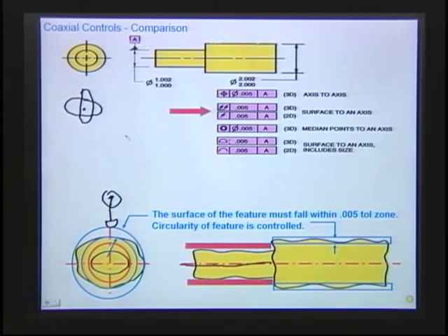So how would you check runout? Well, I'd probably do it the same way. I'd just grab a hold of that diameter, the datum, and then I'd put my indicator on, rotate it, and watch how much the needle moves. If it reads, let's see, our tolerance here is 5. If it reads 5 or less, it's good. If it reads 6, it's out, right? Or remember with position, you would be allowed to further evaluate it, and if ovality was in there, you could take it out, but with runout, it's out, that's it.